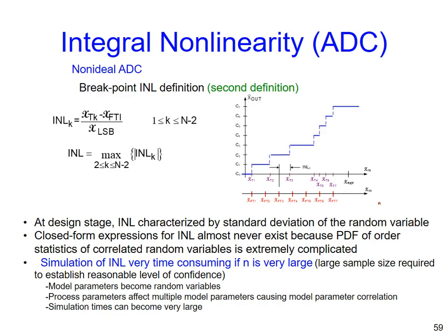Okay? Since INL is the most important specification for your own design, you will see even the simulation of such INL usually takes a lot of your time. But before that, you need to resize your transistors, resistors, a lot of parameters to fine-tune, right?